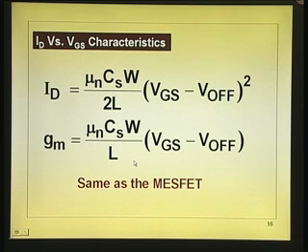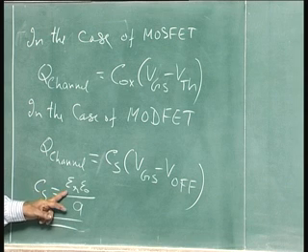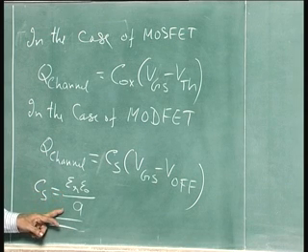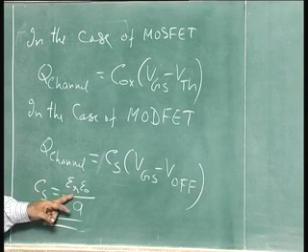Now, you can see you get better and better transconductance if you have better mobility. And since the gallium arsenide layer is undoped, there is no impurity scattering. So, at room temperature itself you will get about 8500 centimeter squared per volt second here, and CS you would prefer to keep large, to keep GM large. Compared to MOSFET, CS will be large compared to C oxide for the same thickness, because the C oxide formula is the same as this, except this is epsilon oxide.